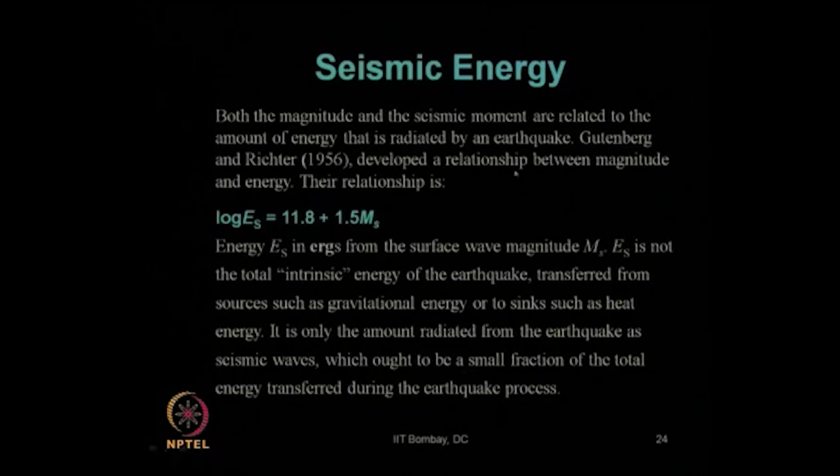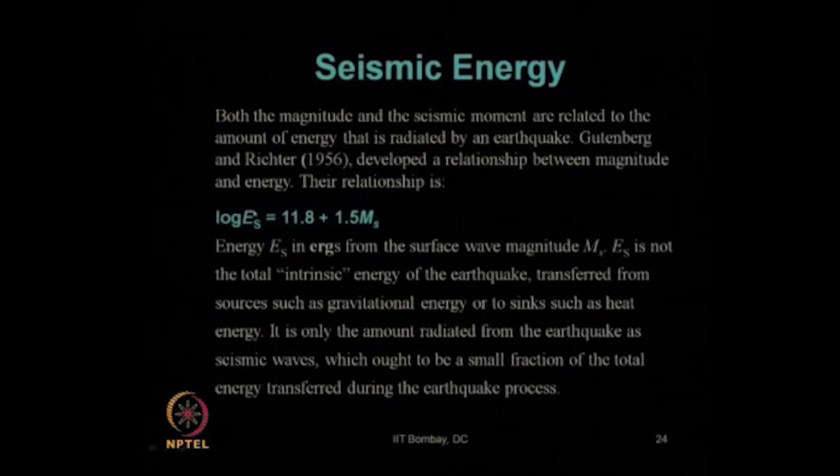So, what Gutenberg and Richter mentioned, if you are using this equation to estimate the energy, is that your estimated energy is related only to the amount of seismic wave, or more precisely the amount of surface wave only. It is not related to the energy which is lost during the transfer through heat energy or sound energy, all these losses. So, you are not able to get the exact amount of energy which is getting released.